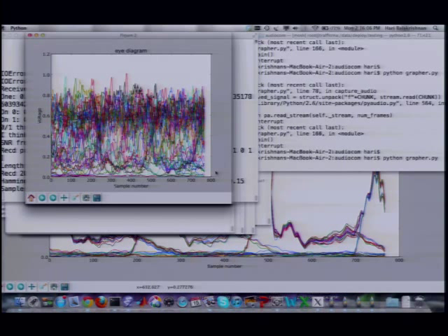Uniform noise? Yeah, you mean if you were to make another transmission at exactly the same frequency. The beauty of this is that there are different demodulation schemes. Right now we're using something called envelope demodulation, which Professor Verghese talked about before. All that's doing is taking the absolute value of every received sample and then running a simple averaging filter. And that's what you'd write in the lab. It's a very, very simple demodulation.